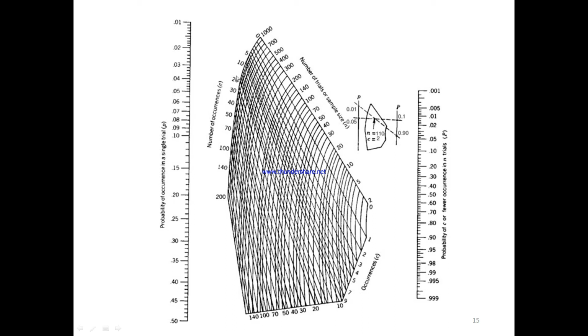So you can join these 2 points using a straight line, and let's say LTPD value is 0.05, it's somewhere here, and let's say beta value is 0.1, it's somewhere here. So you can join those two values as well, and at the intersection point you can see in the graph, these are the C values, and these are the sample size values. So at the intersection point, if you read, you will get the sample size as 110 and the C value as 2.